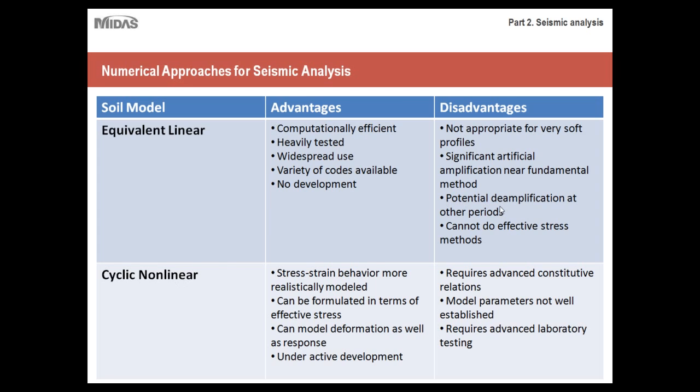Just before I continue, there's potential deamplification at other periods, which is another way to say that certain assumptions are made as far as your time history graph. And then it can't do effective stress methods, so it can't take undrained conditions into account.